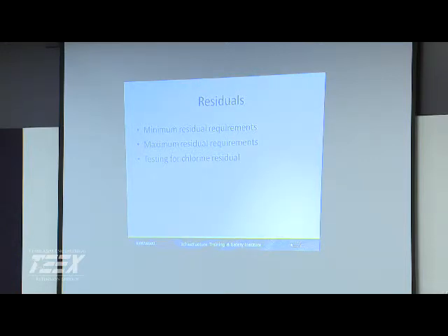But it's also important to know how to calibrate it, because how can you verify that data or that number that you're getting if you don't know how to calibrate it? So are y'all doing primary standards, secondary standards? On the CL-17? For your pocket colorimeter, the electronics, we calibrate it every time we run a test with the, I guess, secondary.